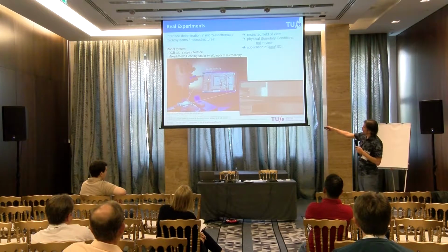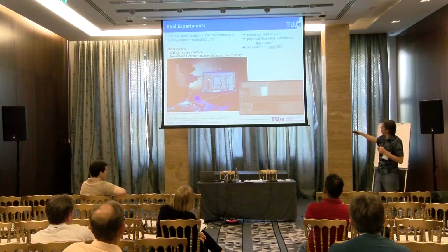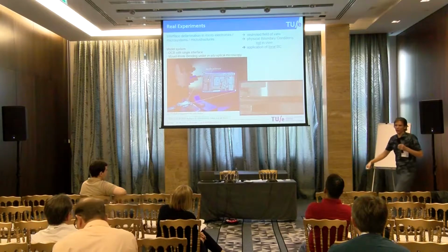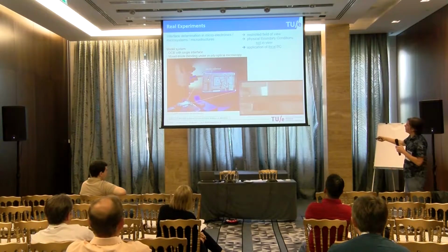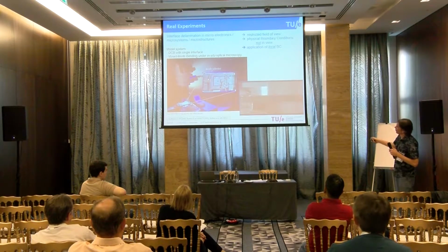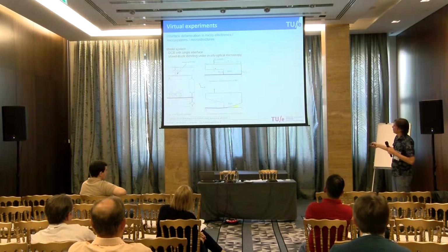So we're going to use a model system. This is, of course, way simpler than a computer chip. This is, again, this double cantilever beam specimen, and we're zooming in here. We actually do have access to the forces, but we assume we don't. We're doing a mixed mode test here, basically the Reeder and Crews mixed mode bending test. We have a miniaturized version of this, and we do this under an optical microscope and get these kinds of movies. We're going to assume we just zoom in on this subregion here.